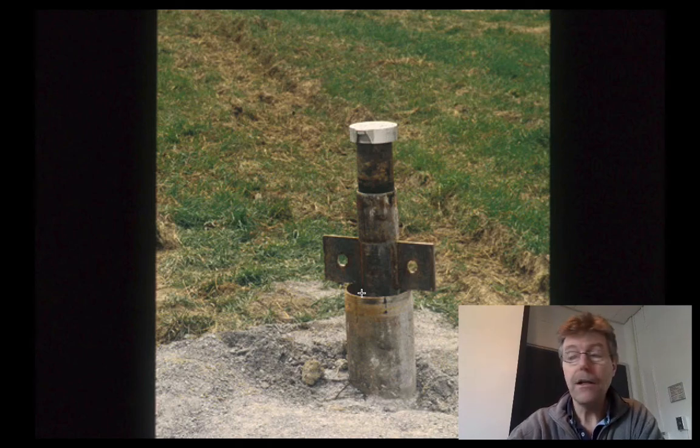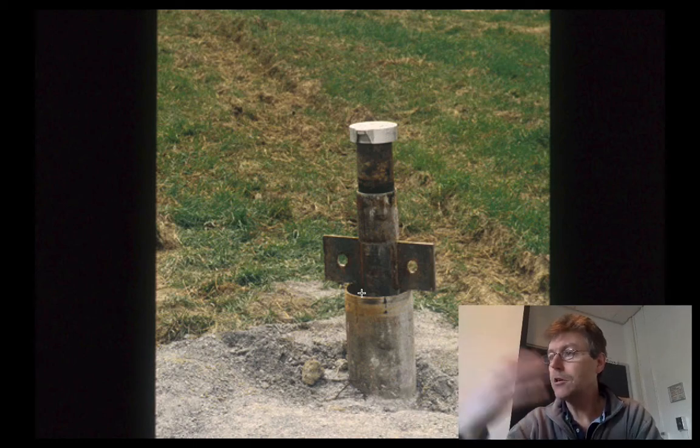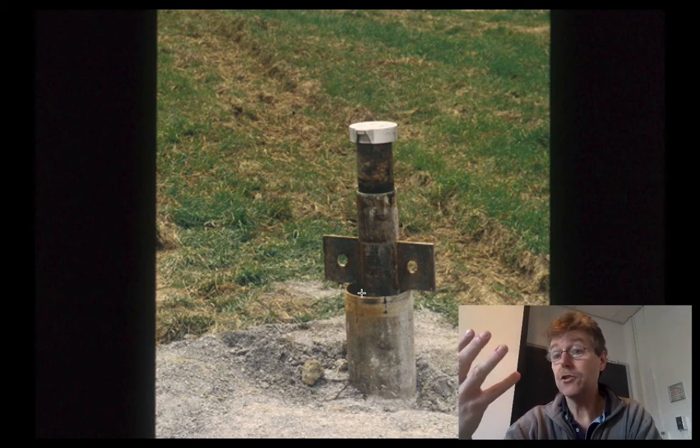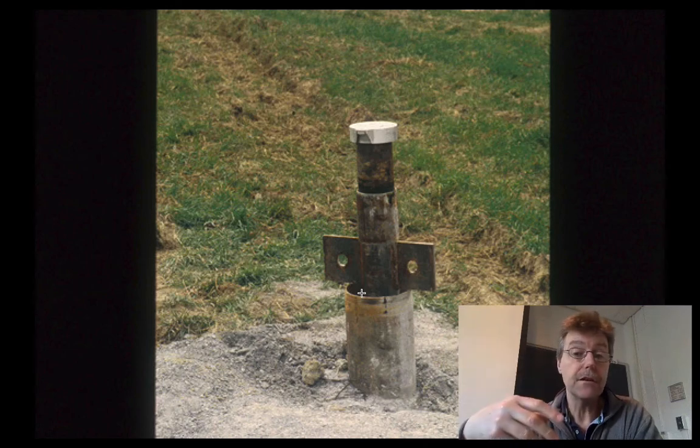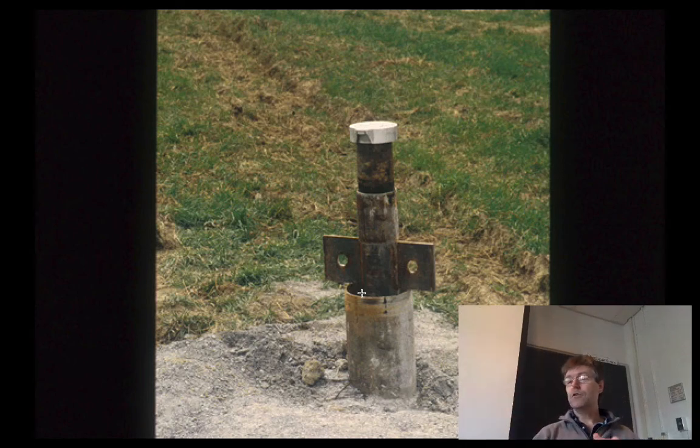The idea is that fly ash you don't want to have, it's a pain, because you burn coal, you end up with fly ash, you have this big surplus which you can't use as a byproduct. You have acid mine drainage, and so maybe you can put fly ash into the ground to do two things. You can stop the drainage by filling up the mine voids so there's not so much water going through them. You can also fill it up so it takes care of the air because it's now saturated and you won't get the reactions that cause it.